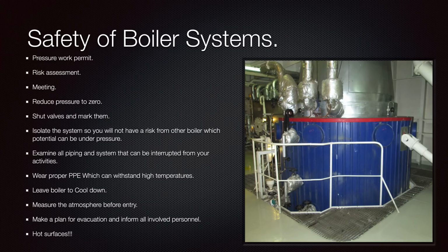First of all, when we are working with the boilers, we need to make a pressure work permit. Whatever we are doing, we must be identifying if our boiler is pressurized or not. So this is what the pressure work permit gives us. There is some checklist, and you're running through that checklist and you're checking all those stages. And at the end of that, after your identification of all the problems and risks that are associated with the pressure, you can do your job safely.